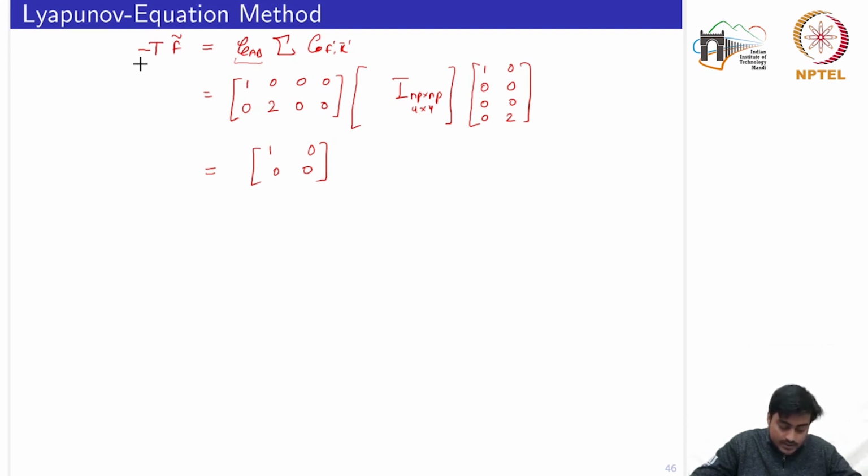So now the problem arises that either we keep iterating to find those K bar such that two conditions are satisfied, that the pair (F transpose, K bar transpose) is controllable and the matrix T is non-singular, or we should search for another design method by which we can compute the matrix K in one shot.